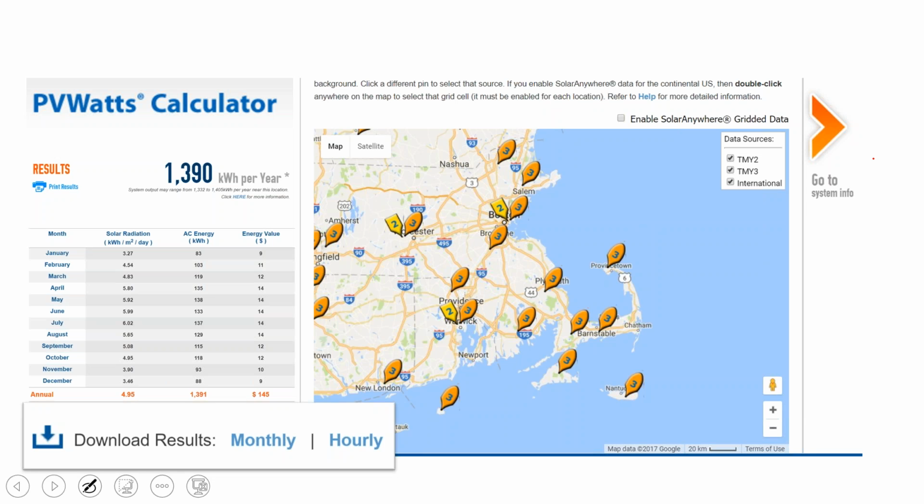So, as we mentioned, where do you find temperature data about your job site? Well, a handy dandy PV Watts calculator, the same calculator you can use in a matter of minutes to do an energy performance estimate. It's all free. It's put out by the Department of Energy. We have all these public weather monitoring stations at airports, at military bases that are collecting weather data all the way back into the 60s. And so what PV Watts does, it's governmental software, and it gives you access to this weather data and puts a solar performance calculator on top of it.